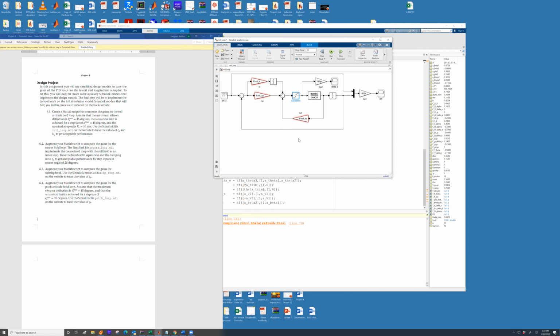This, yeah, just the roll autopilot slide that I just showed. You can find those values and substitute in here. But here is what should happen. I'm going to say my Kp value is 1, my derivative value is 0.5, and my integral value is 0.01.